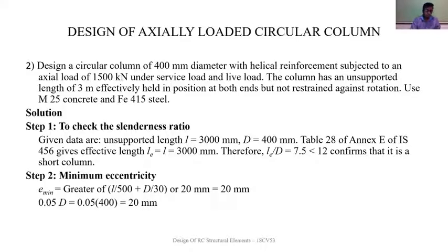The second point is maintaining the specified ratio of volume of helical reinforcement to the volume of core as specified in clause 39.4.1 of IS 456.